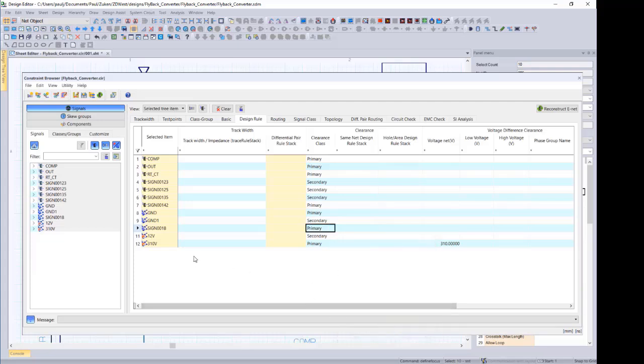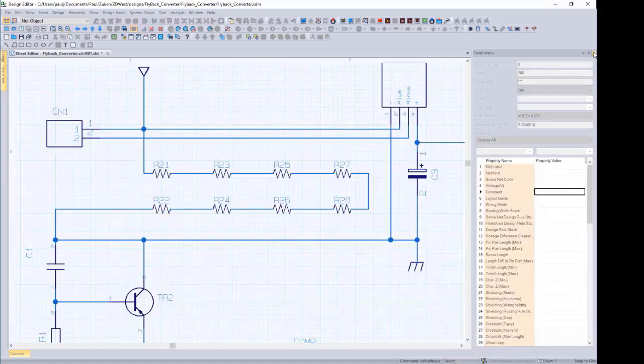Now I know from looking here, I can see that all my nets are actually allocated into a clearance class. But on a bigger design, this could be pages and pages of net names. I might miss that something hasn't had a net assigned, which is why I said to try and capture those with a large rule at the class-to-class clearance configuration. Okay, so I can just close that.